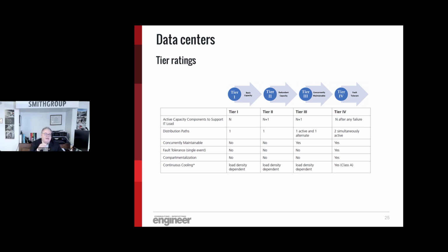What you find is that there are some data centers that rigorously follow these tiers, and they actually go through the Uptime Institute certification. They cannot officially claim a data center as a tier 2 or tier 3 without going through that certification. What you will find, though, is that many of the data center operators will tell a designer, I want tier 3-ish, close to it, but they'll take some not exact requirements. So you have to look at that closely and discuss with the client what level of reliability they're getting into and really what amount of uptime and concurrent maintainability they want.